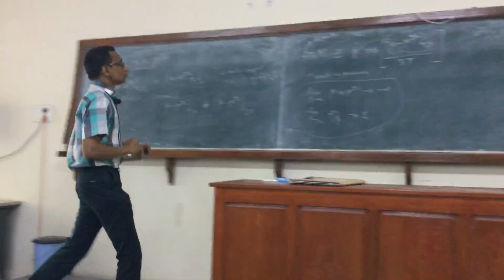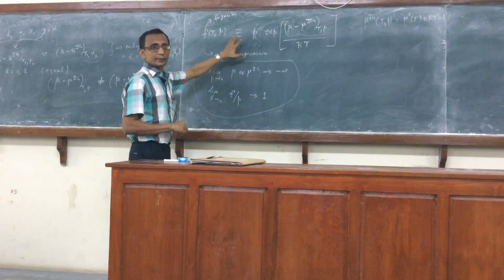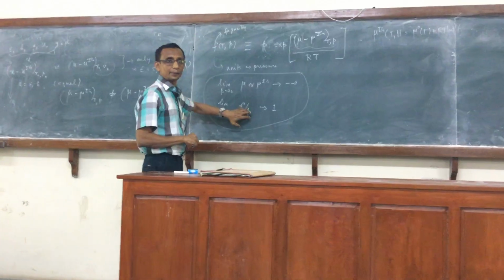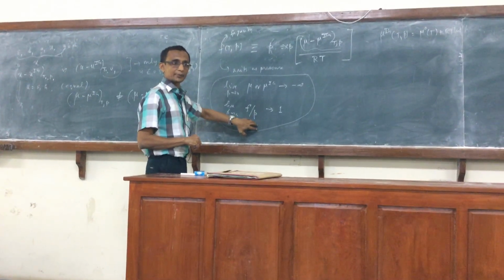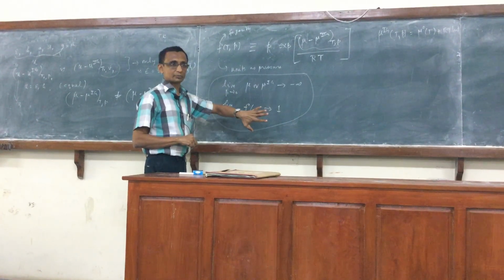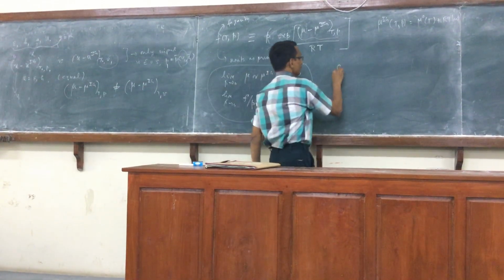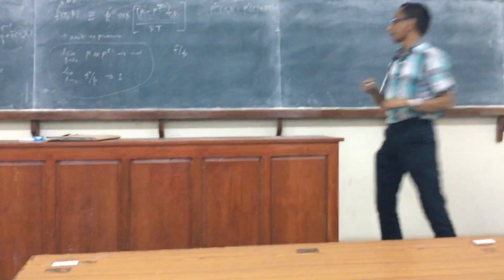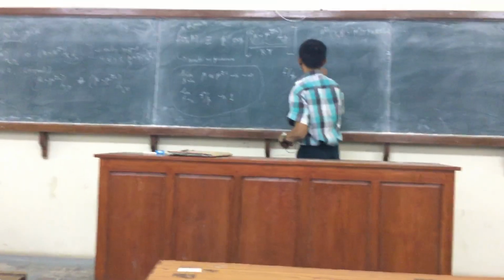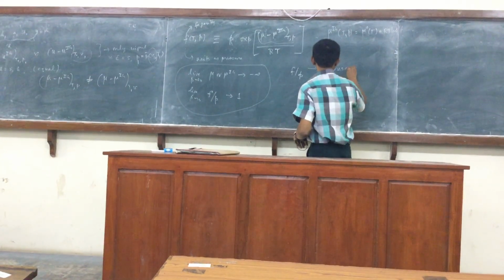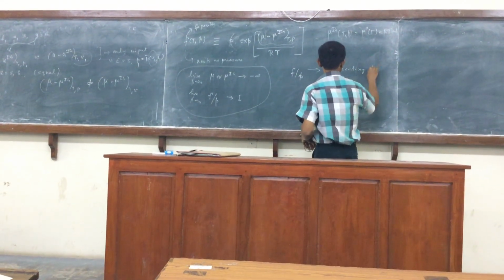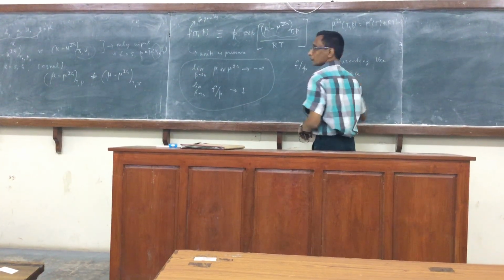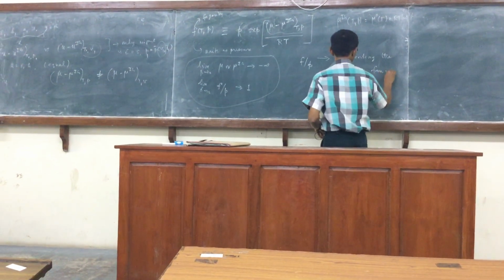Another way of looking at this is that since at low pressures, that is, in the ideal gas limit, the fugacity of the actual substance tends towards the pressure, you can regard the ratio f over P, in general at all pressures, as representing the deviation from the ideal gas behavior.